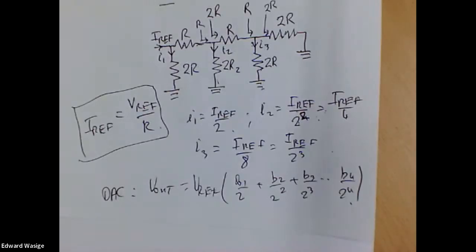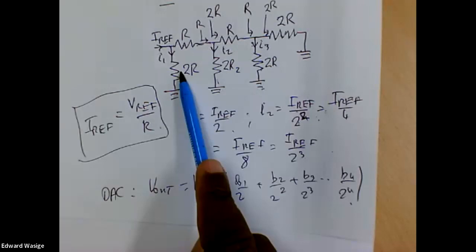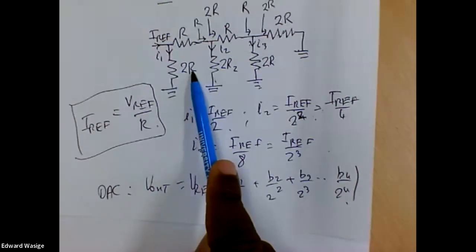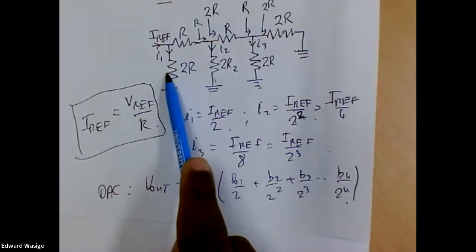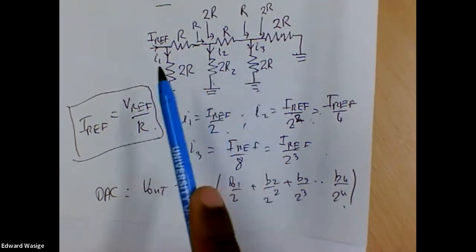And do we want the resistors to be large or small? If they're too small, this is an engineering judgment you have to make, Mohammed. If the resistors are too small, the current is quite high, and so the I squared R loss becomes an issue. The chip will heat up quickly because of I squared times R; it becomes like your old bulbs, like a little heater.